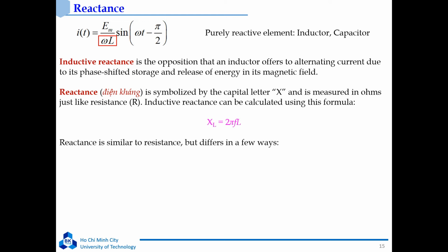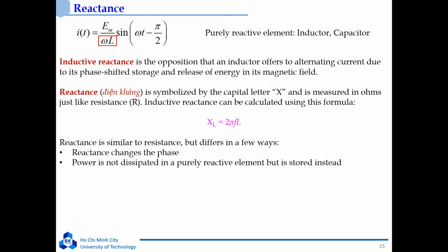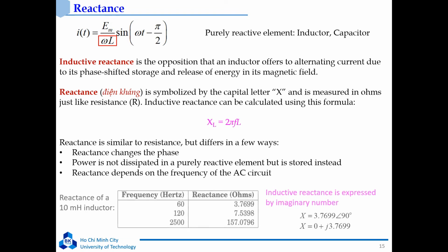Reactance is similar to resistance, but the difference is in phase. Reactance changes the phase. The power is not released into the environment in a purely reactive element, but is stored instead. Reactance depends on the frequency of the AC circuit. You can see the reactance of a 10 mH inductor in this table, and reactance is expressed by an imaginary number.